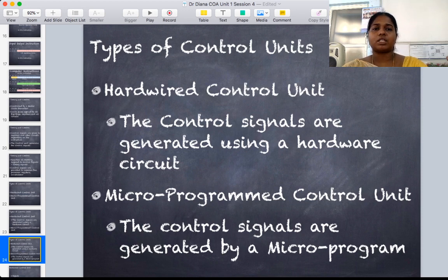At the next clock cycle, you add both of them and put the result inside the accumulator. Likewise, the sequence in which the operations are done is written as micro operations, or as a microprogram, in the memory. And every time the control unit wants to do something, it will ask the memory unit what it has to do.